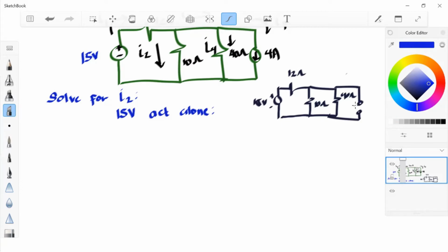First and foremost, we need to solve the total resistance at this point, where we put an ohmmeter right here. So what is RT? Our total is 12 ohms plus, using product over the sum because this is a parallel circuit, 10 multiplied by 40 over 10 plus 40.